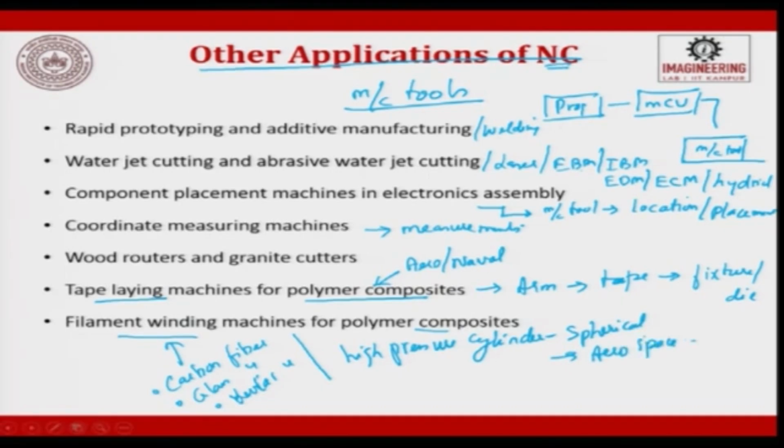It is like a shell, something like this. So, you will have a fabric which goes everywhere, and you can also use these filament winding machines to wind the pipe, wherein you need to have very high compressive, very high hoop strength.